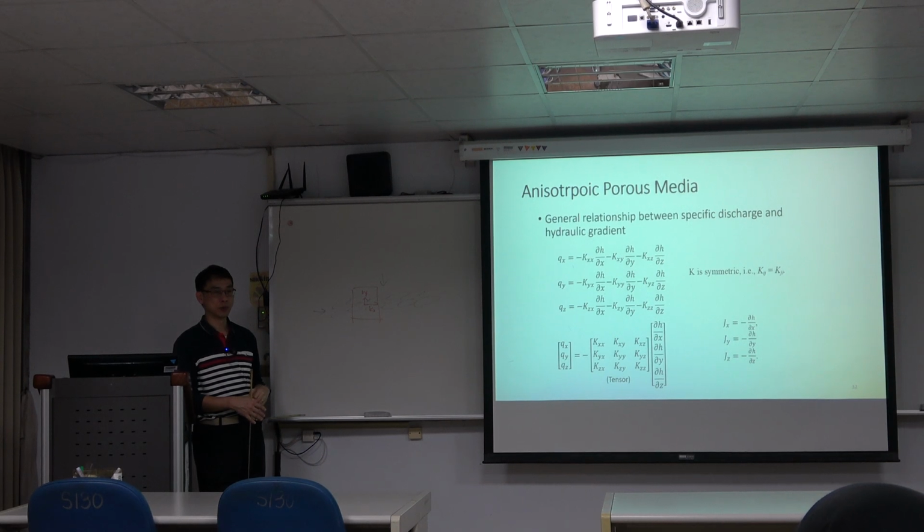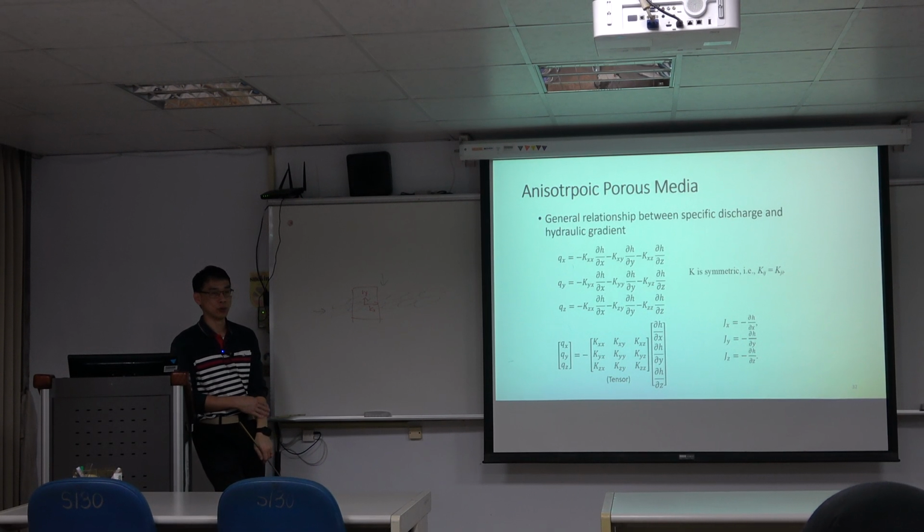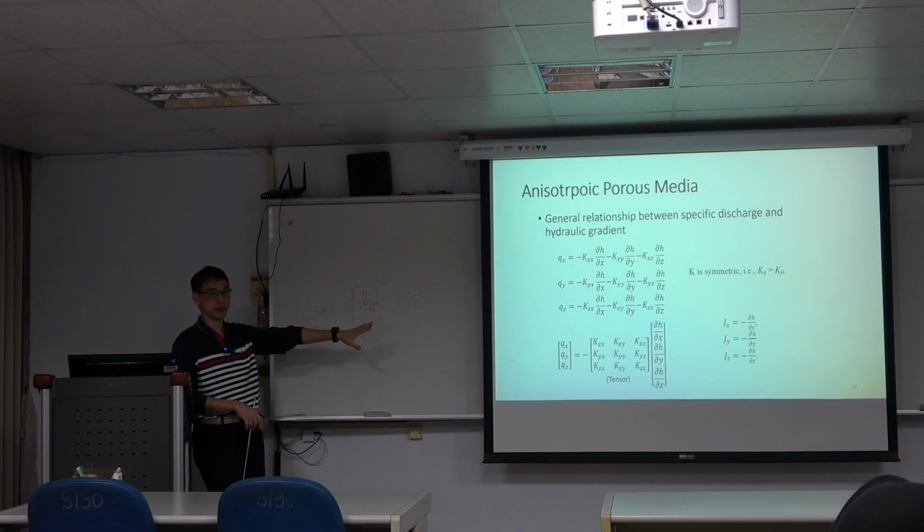But if we would like to more completely assess this kind of behavior, we should include the tensor. For sedimentary issues, right now we still do not have these kinds of complex tensors. We were using Kx, Ky, Kz only. We're not using Kxy, Kyz like that, which is complex. But for rock fracture systems, rock mechanics, right now they try to include more of this kind of tensor system.